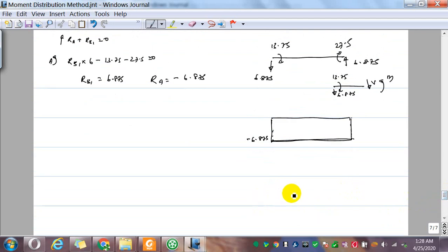And if you consider the bending moment diagram, so this is the shear force diagram. You consider the bending moment diagram, so you have a fixed end moment here, that is 13.75. This is positive because it's going to sag that element. So it is sagging, so it's positive, that is 13.75, and then here you have a moment 27.5, that is hogging, because it tends to hog the element, so it's minus 27.5.